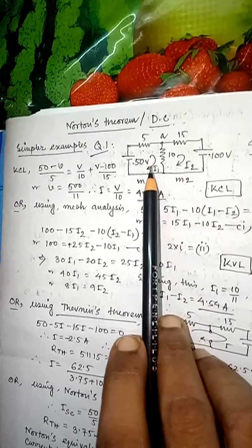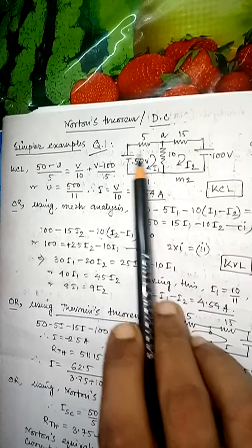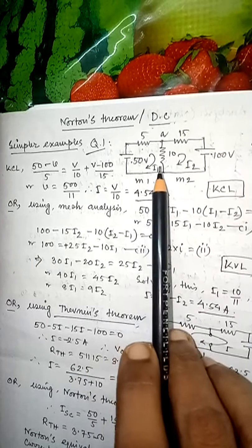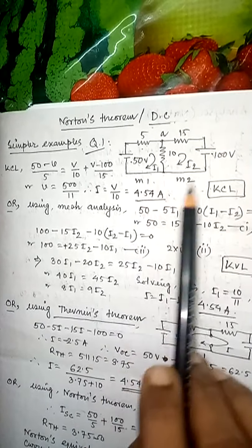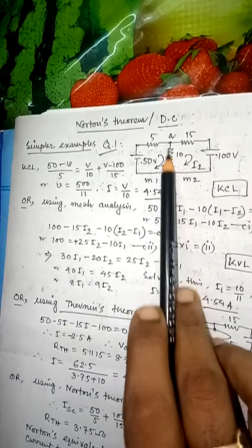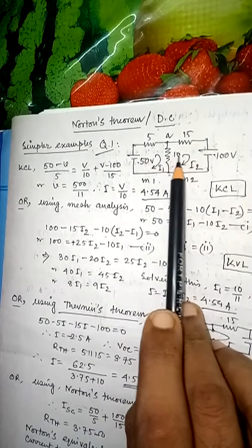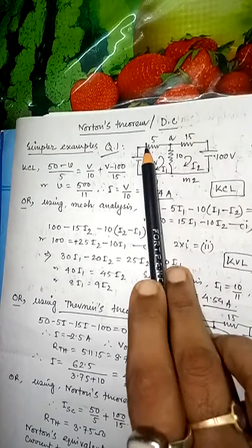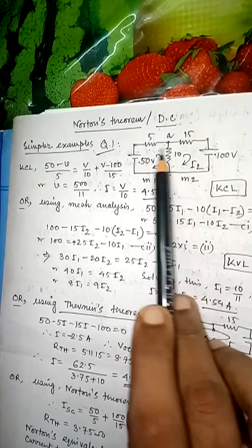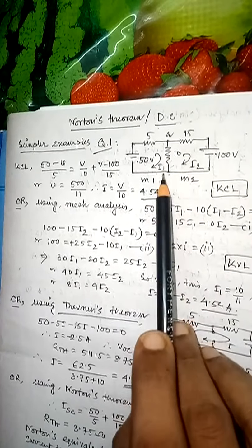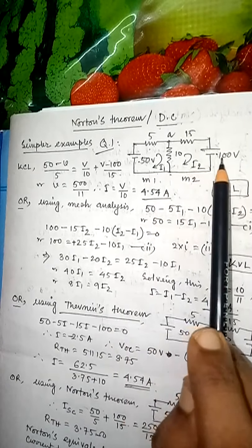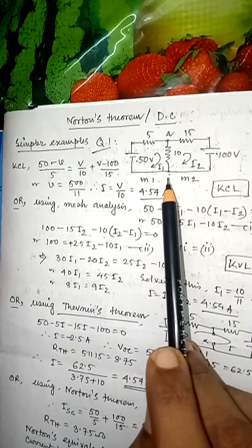If you have knowledge of Z and Y parameters, you can easily use it and find out the short circuit parameters, or the Z parameters, or the open circuit parameters, or anything else, depending upon how you write that equation. Basically this type of circuit is called the T circuit. It is a T-like combination. It can be easily converted to the pi circuit also. If you are converting to the pi circuit, these values will change. How? That is a star combination. So you know how to convert star to delta. This particular circuit will be converted to the delta, and the same thing can be applied on this, and finally you will be able to get the requisite, okay?